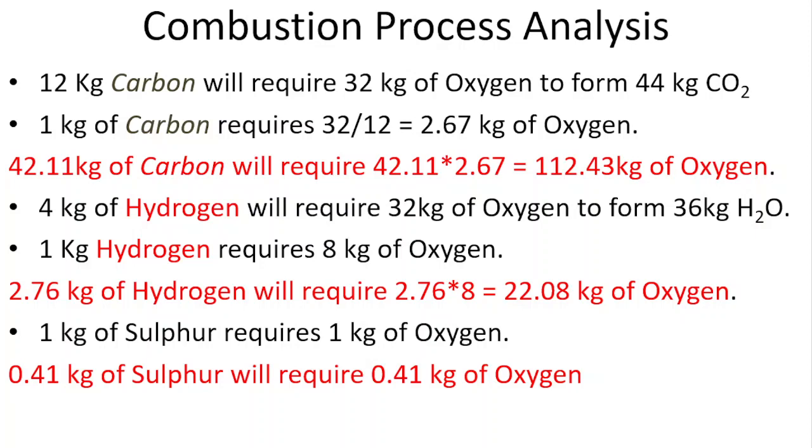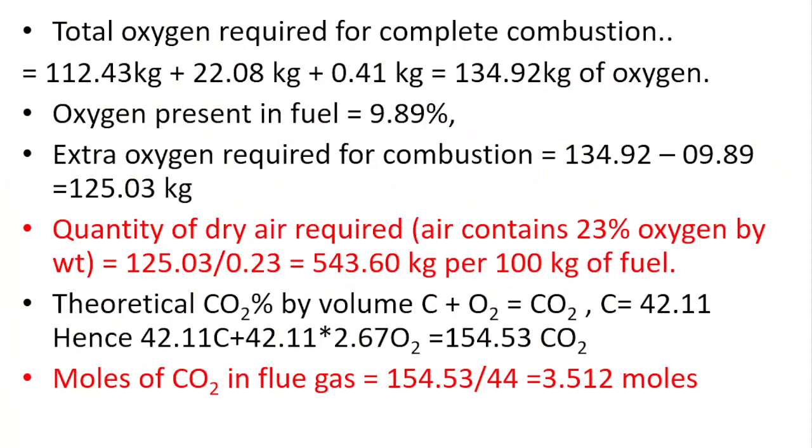Now 4 kg of hydrogen will require 32 kg of oxygen. So from that you can infer that 2.76 kg of hydrogen will require 22.08 kg of oxygen. And similarly for sulfur, 0.41 kg of sulfur will require 0.41 kg of oxygen. So the total oxygen required for complete combustion would be around 134.92 kg of oxygen.